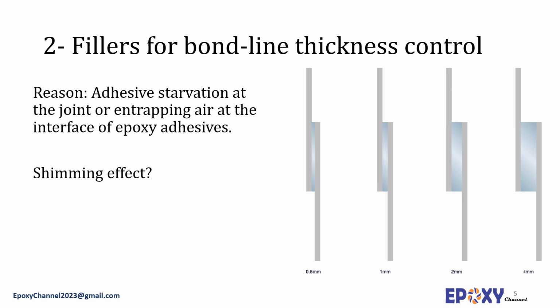On the other side, if the adhesive flows only under great external pressure, there is a risk of entrapping air at the interface and too thick a bond line. These conditions result in localized high stress areas and a reduction of the ultimate joint strength. Flow characteristics can be regulated by the incorporation of fillers or woven tapes referred to as internal shims.